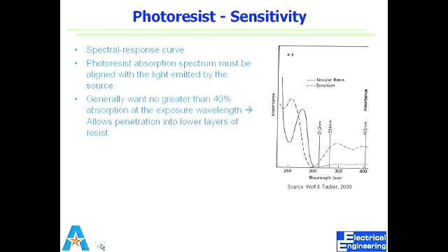This is an essential exercise. If I have a system which has 340 nanometer wavelength and I have this photoresist and this is the plot of absorbance, can I do my lithography? No. Why not? It won't reach the bottom. It won't get absorbed at all, right? I know the y-axis is in arbitrary units, but it shows you that it's almost close to zero, right? Or whatever the minimum amount is given there.